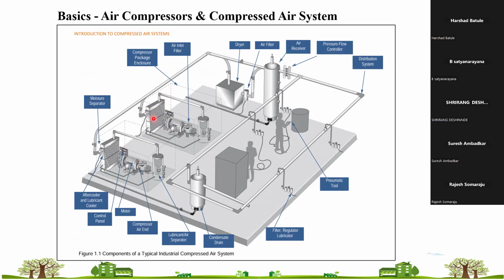So what you can do is give the 200 from this base load. You can set the bigger compressor at base load, and the smaller compressor can act as peak load. This kind of management has to be there for efficient operation of compressors.